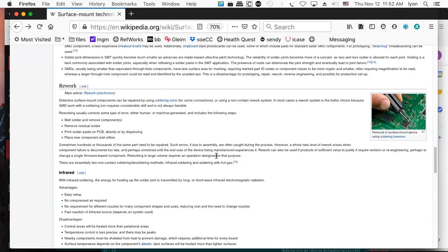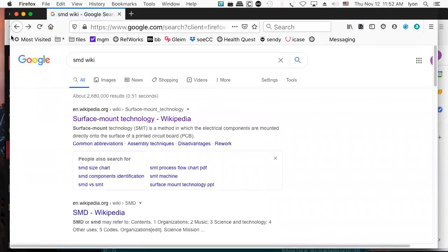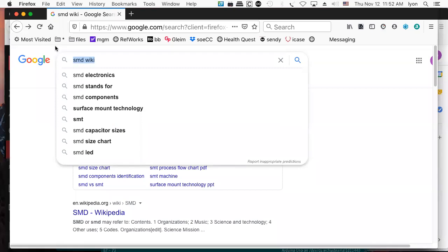But if you want to do a printed circuit board, these are the kinds of questions people ask, because they want to know, are you going to do it through-hole or surface mount? And there's a big difference in the production costs when you do things in a through-hole fashion. Not that they can't be automated, they can be. And in fact, there are places here in Connecticut which will automate through-hole production. You get a sequence machine, it'll go through a bending machine, they'll make a tape that has all the parts you want on a single tape, and then it'll run it through one board at a time and then go through what's called wave soldering. Wave soldering is the alternative to reflow soldering.